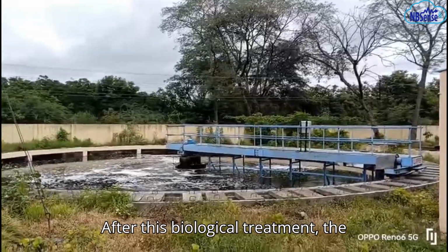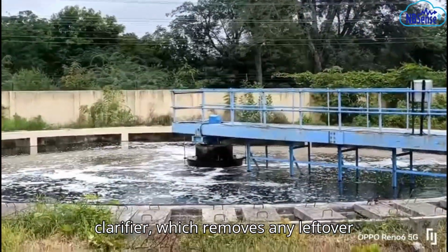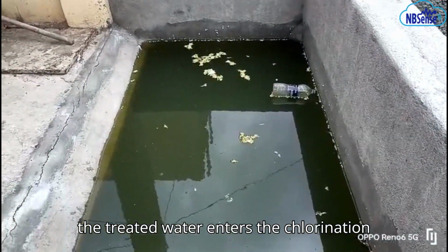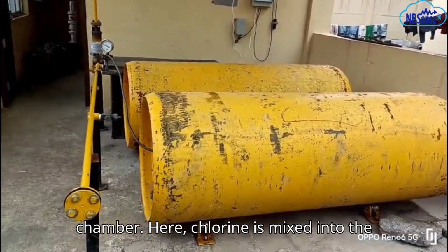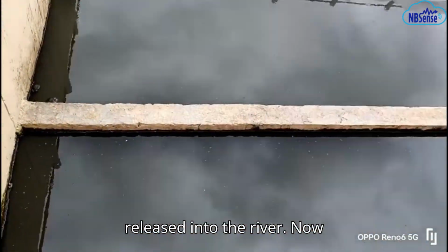After this biological treatment, the water passes through a secondary clarifier, which removes any leftover impurities. Finally, the treated water enters the chlorination chamber. Here, chlorine is mixed into the water to disinfect it before it's released into the river.